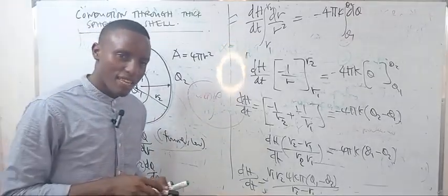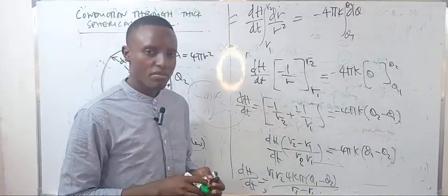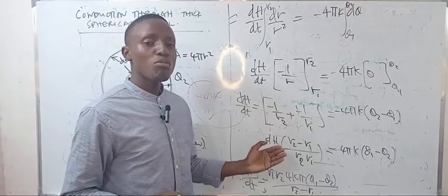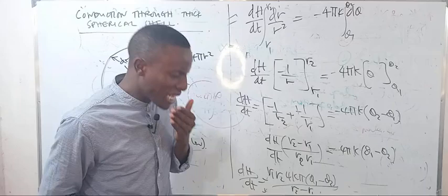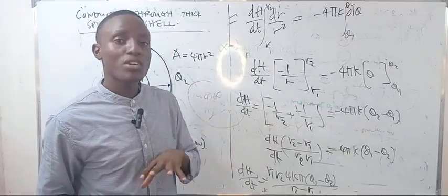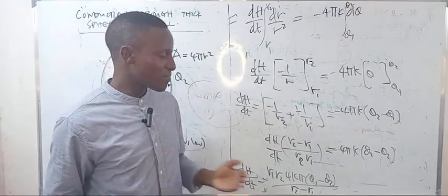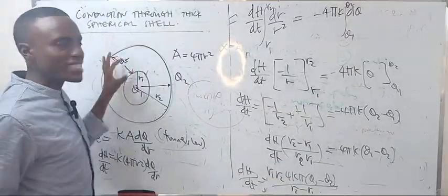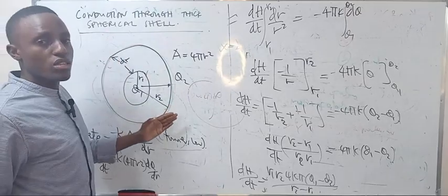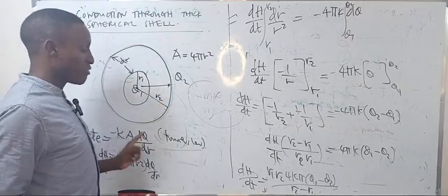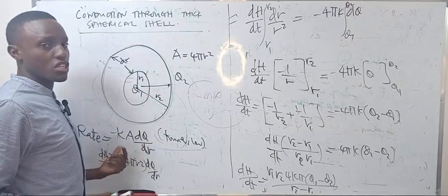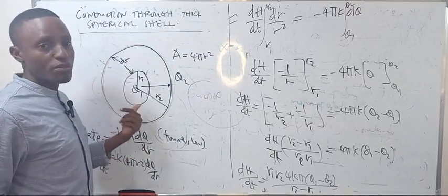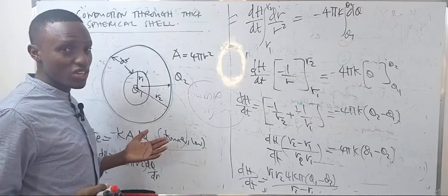If you forgot about everything, don't forget that what you subtract is not the smallest value. For example, for the radius, the smallest value is R1. You don't do R1 minus R2. And if you don't put that negative, that there is a decrease in temperature here initially, you just get the reverse of the formula, so you get incorrect answers.